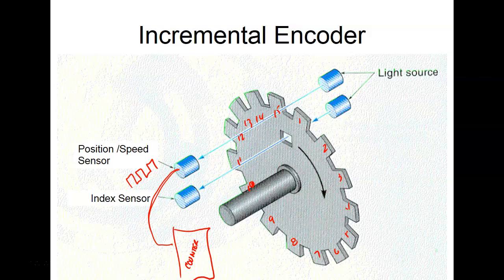So now all of a sudden I've got one encoder. I've got an electronic circuit called a counter. All it does is count pulses, and then over here it would give us a binary number that represents the count. So if I've got a 10-bit counter, it's 0 to 1023. It doesn't make any difference how many petals you have. But once it got to 1023, what do you think it would do? It would roll over, yeah. Just like the old odometers on cars used to do.